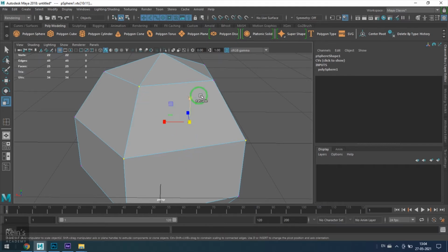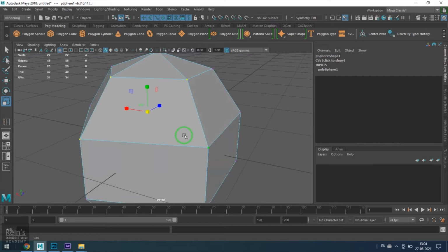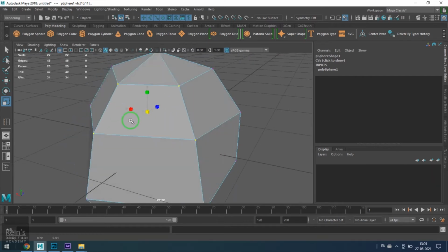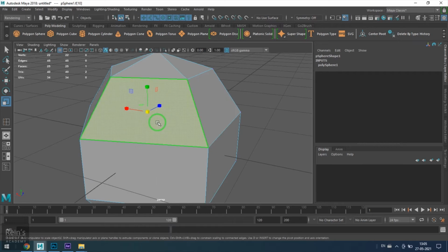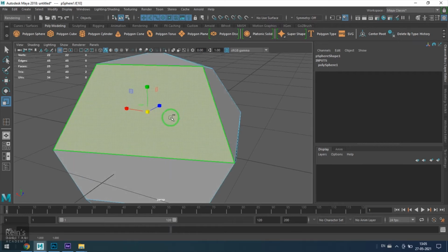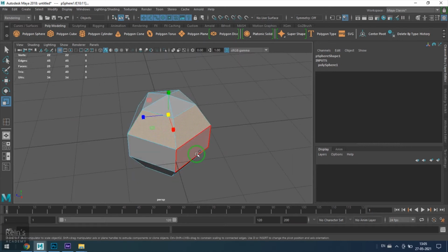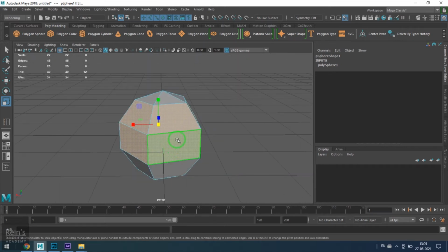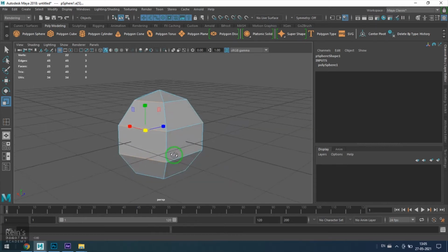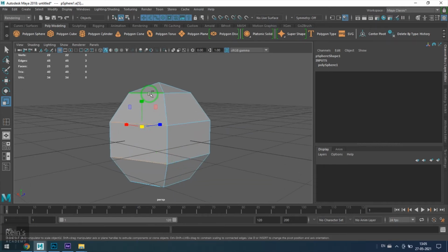Alternately, if I select the 4 vertex points, then scale them, it is the same as selecting the face and scaling it. We can hold and select multiple faces there. It is also very similar in vertex selection and edge selection. If you have selected multiple edges, by holding Control, you can deselect them.